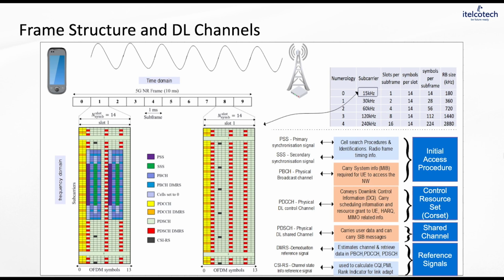So in 5G new radio, efficient use of time and frequency domain is key to achieving the flexibility. Now, here we are taking one example to understand more about the different channels and signals that are present in 5G. So in a radio interface, we have the frequency and time domain grid, where we have different resources allocated for different purposes. We have logical and physical channels that are mapped onto these resource elements to serve distinct purposes.